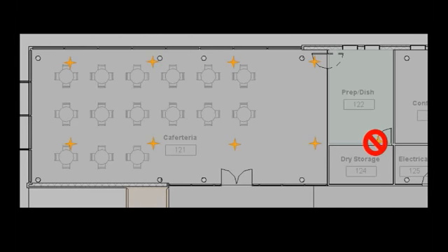Then we're going to look at, are these spaces inside the room? If not, we're going to get rid of them. This takes care of L-shaped spaces, just weird shaped spaces where you did this and the math didn't work. Now for the return diffusers, we're going to find all the doors for each space. From there, we'll find the wall that hosts that door, and we'll get a vector from there.